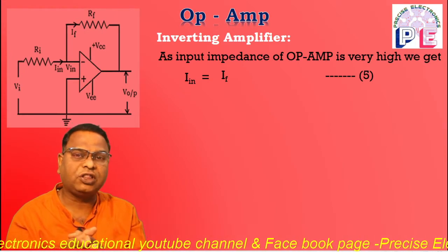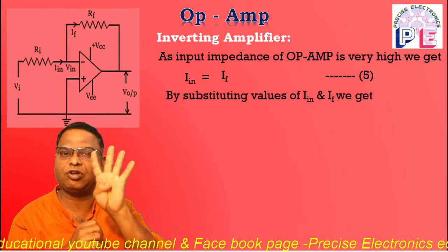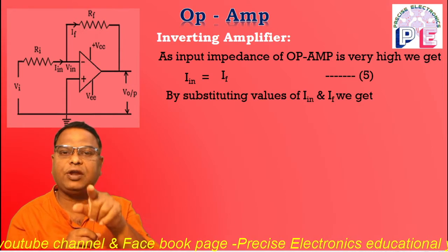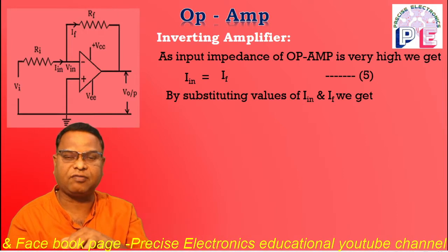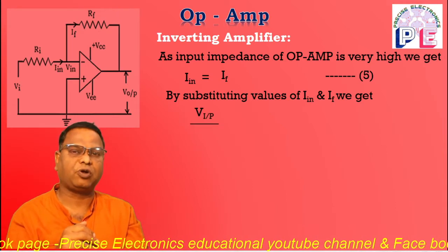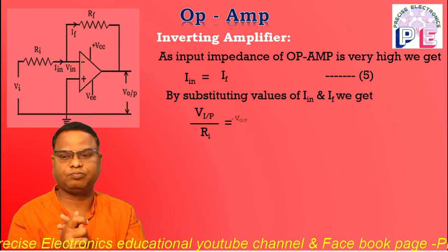Now by substituting the values of I in and IF, that is equation number 3 and equation number 4. What is equation number 3? I in is equal to V input upon Ri. Equation number 4, that is IF is equal to minus V output upon RF. By substituting these values, we get V input upon Ri is equal to minus V output upon RF.